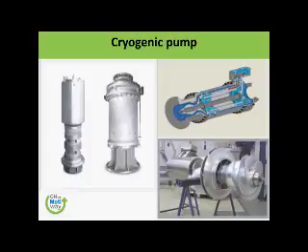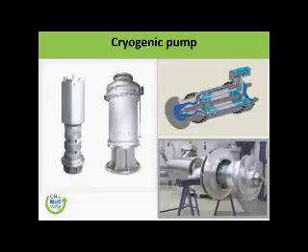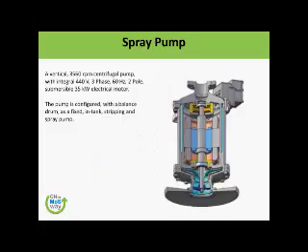In addition to the 2 main cargo pumps, which are huge pumps in the normal LNG carrier, of course, they are small in the other vessels, we have also got the small pump, which we refer to as the spray pump. It is just a 3560 RPM centrifugal pump, 440 volt, 3 phase, 60 Hertz, and of course a submersible 35 kilowatt electrical motor is working